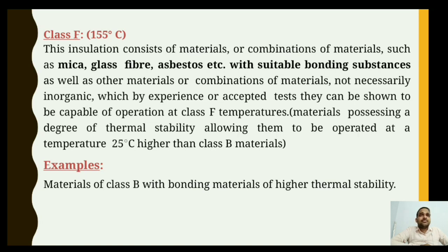But in class F we are seeing that the organic and inorganic substances get bonded with each other, but here it is not necessary to include inorganic materials with the organic substance. The limitation is there for class F, for 155 degrees Celsius, it is not necessary to include inorganic materials with organic substance. We can consider it as an exception.